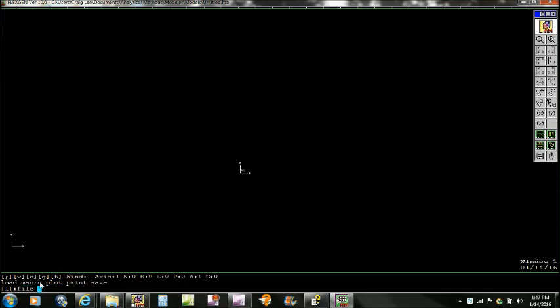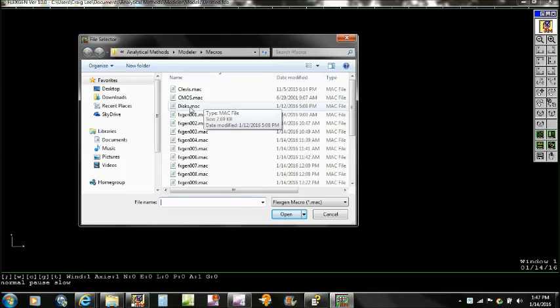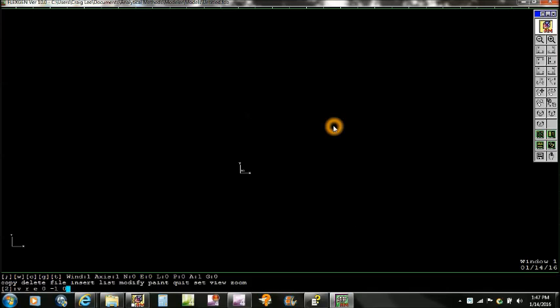and now we do a File, Macro, Run, and we're going to do it in the pause mode so that we can discuss what's going on. And here we come, and we'll double click on disks.mac. So the z-axis is going to be the axis of the shaft that it's on. We'll be building a cross section of a disk first, and we're going to do a little rotating of the axis system here. I know you can hardly see it, but that now says Z there and X in the other direction here.